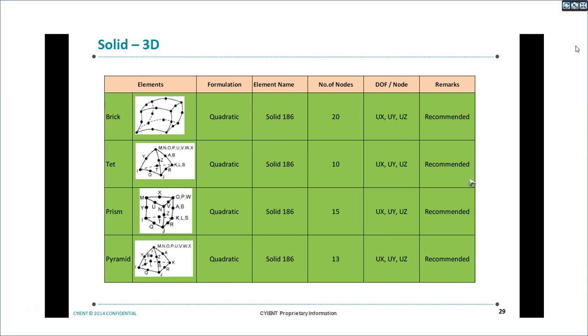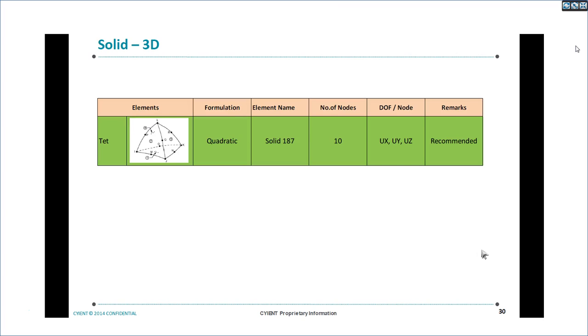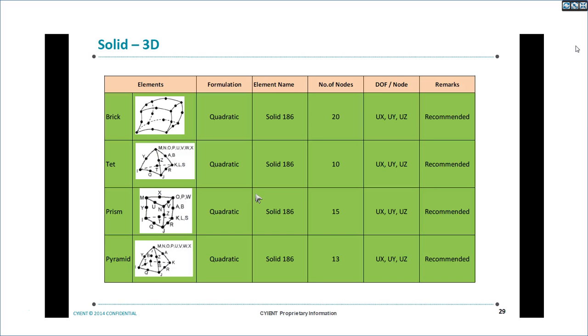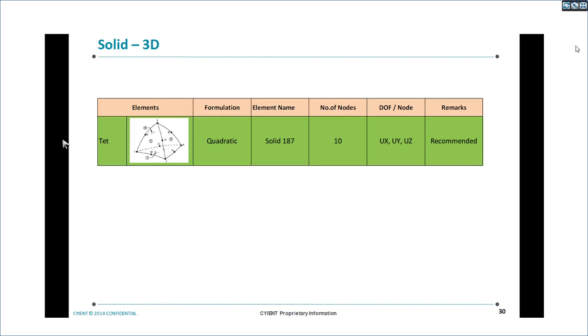TET 10 noded is recommended. Prism 15 noded is recommended. Pyramid 13 noded is recommended. Some typo is here, so same thing, TET 10 noded is also recommended.